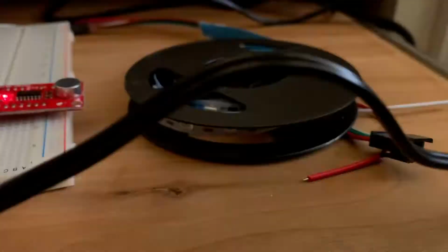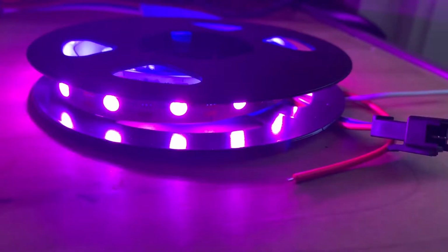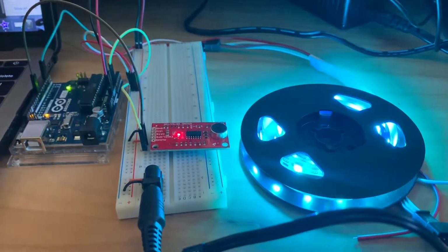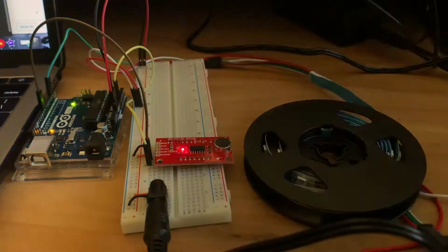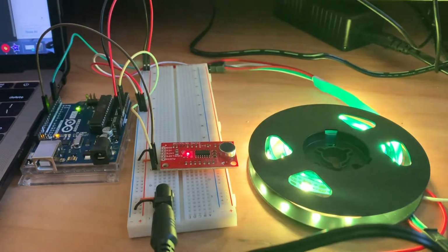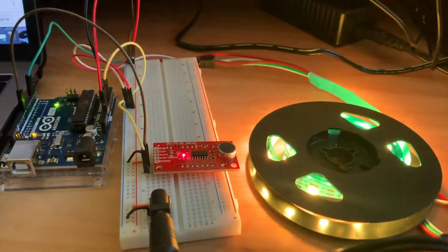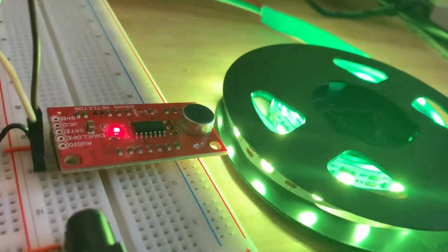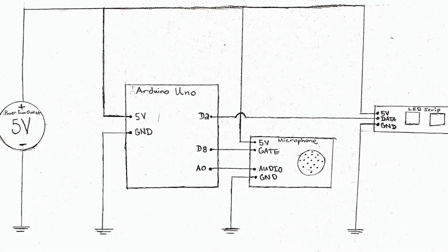I also wanted the LED strip to appear as if it were pulsing to the beat of music. For this reason, I focused on the first bucket of the Fourier Transform, the one which contains signals between 0 and 1250 Hz. I established some small relative threshold, and if this bucket's amplitude change was greater than that threshold between sampling periods, I turned the LED strip off for 50 milliseconds to make it appear as if it were pulsing. This schematic here shows the final circuit.